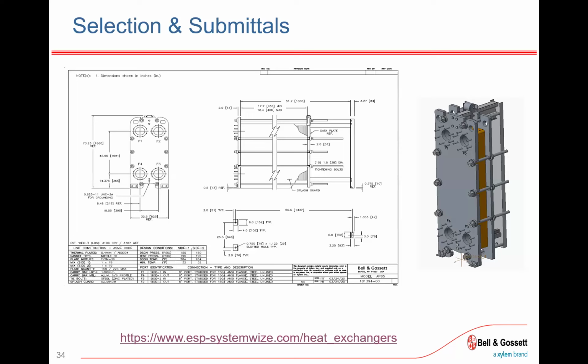So if you were to have, let's say, a primary secondary header, I would actually prefer that sensor not be on that and be downstream on your system, so that you have a true indicator of what your system is achieving downstream. For anyone online, we're talking about the location of a sensor on a primary secondary header.